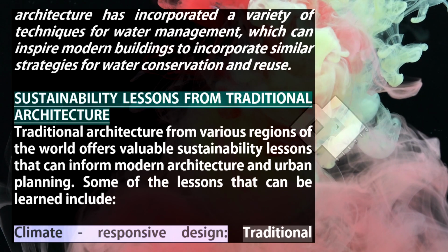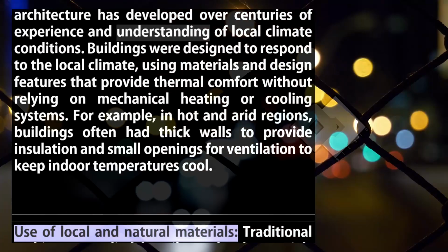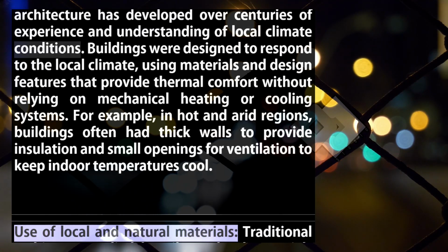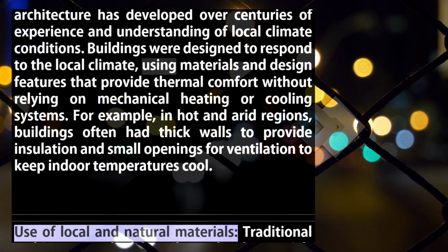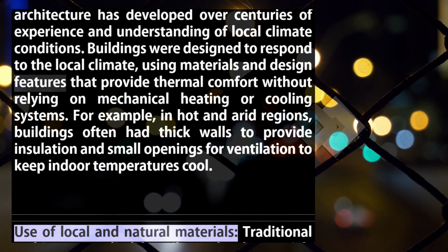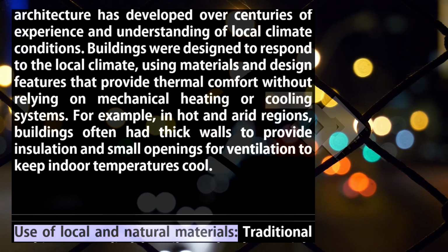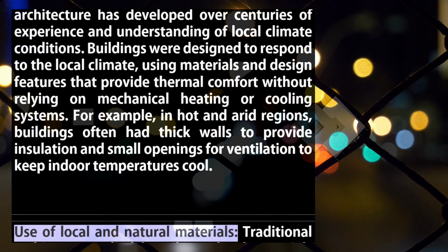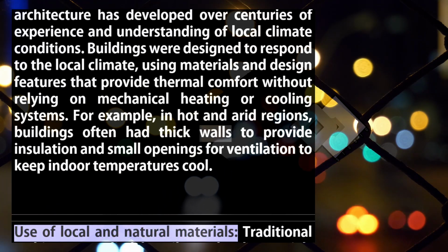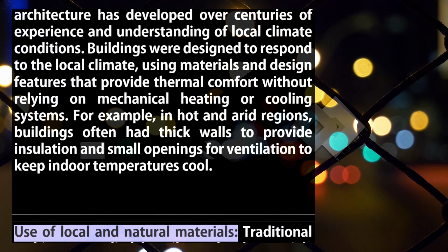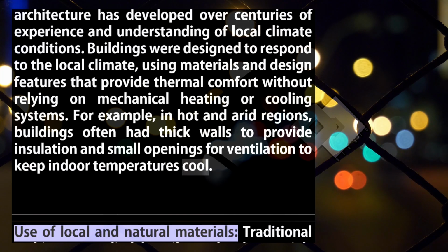Climate-responsive design. Traditional architecture has developed over centuries of experience and understanding of local climate conditions. Buildings were designed to respond to the local climate, using materials and design features that provide thermal comfort without relying on mechanical heating or cooling systems. For example, in hot and arid regions, buildings often had thick walls to provide insulation and small openings for ventilation to keep indoor temperatures cool.